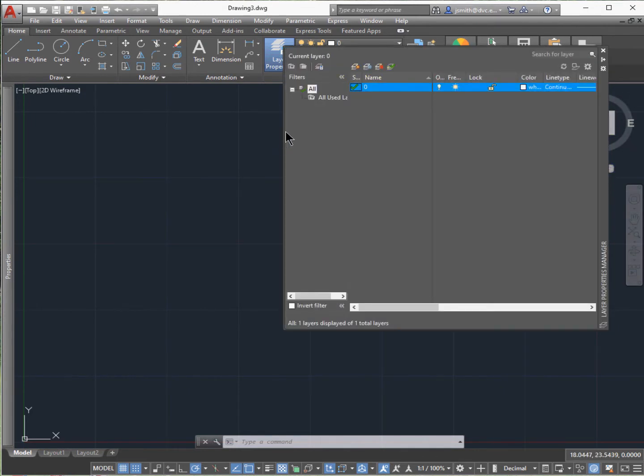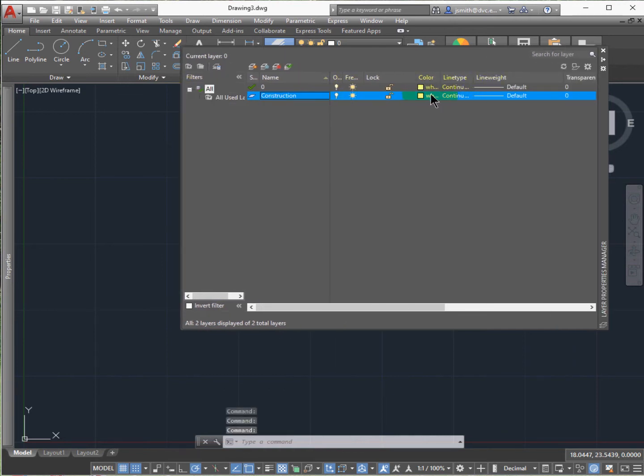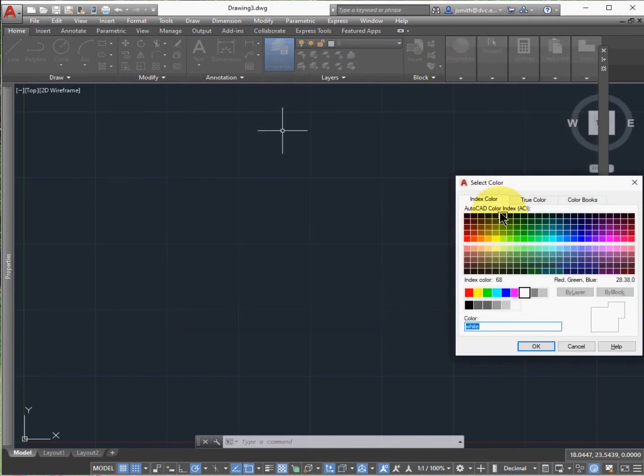And so hover over it, create the new layer, and then it automatically defaults into the typing mode. So we're going to go ahead and type in construction. And I'm going to go through this layer by layer, and you'll notice that some layers have gray and white, and also the types of lines. There's hidden and center lines, and there's also a line weight.